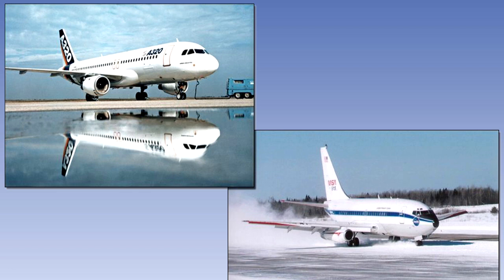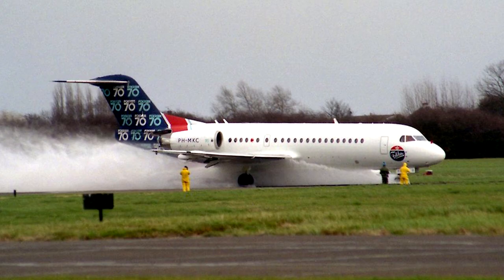Standing water, snow, and slush behave in a similar manner to the effect of grass in that they create additional drag as the wheels pass through them. But they also create additional drag as the spray from these substances impinges on the aeroplane. This is known as impingement drag.